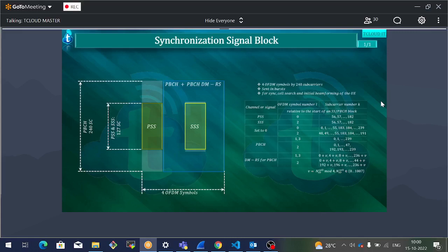All other channels, except some special channels present in the synchronization signal block, would be using the modulation techniques that we have studied. What modulation techniques am I talking about? QPSK, BPSK, etc. So if the mobile equipment downloads any particular carrier bandwidth and decodes it, it will get all these 1 by square root of 2, 1 by square root of 2 j symbols. But a newly arriving mobile equipment cannot detect which symbols belong to which channel.